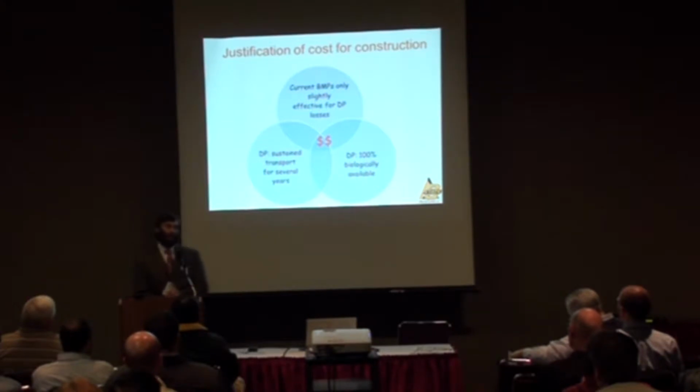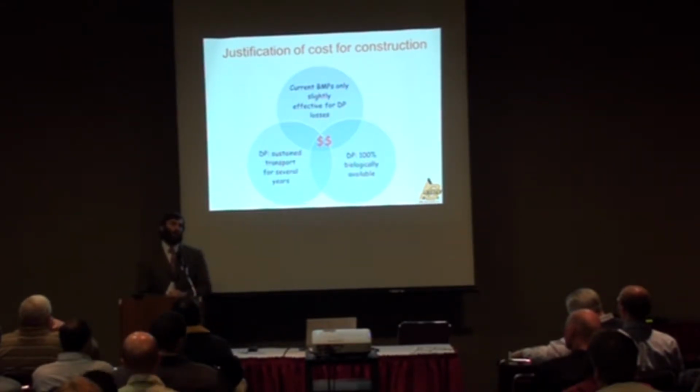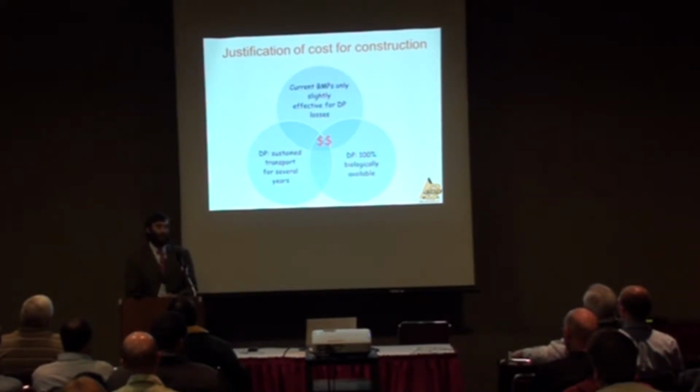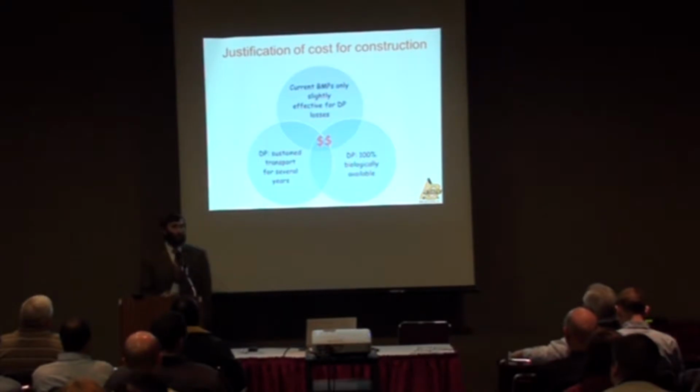Another important factor is that dissolved phosphorus, once it reaches a water body, is 100% bioavailable. That's not necessarily true for particulate phosphorus. Particulate phosphorus may or may not be bioavailable when it reaches a water body. It may absorb phosphorus. It depends on the mineralogy of the sediment and the conditions of the water body that it's reached. So these three factors together are justification for constructing some of these phosphorus mineral structures.